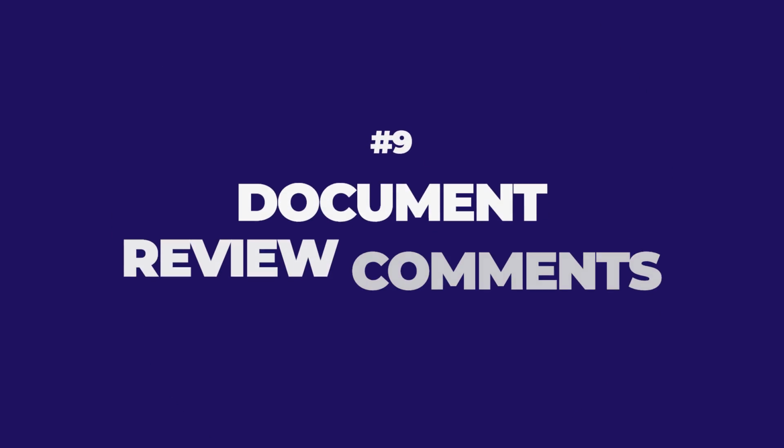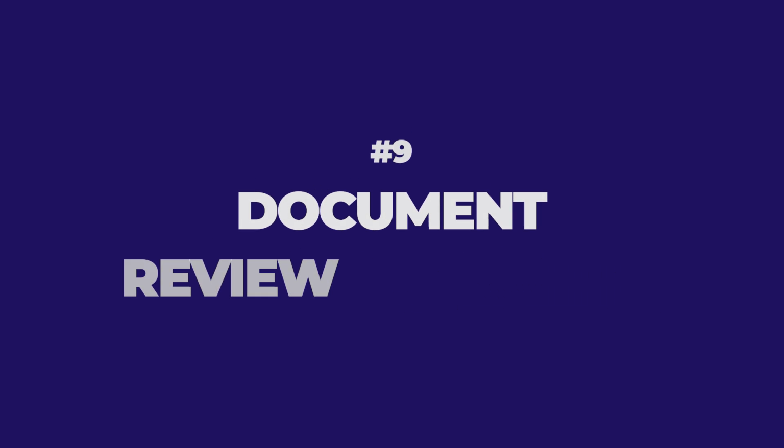Number 9, document review comments. Clearly provide review comments and feedback. And if you can, deal with that issue right then and there instead of not approving it and hitting it back into their court. If you can fix something and make that submittal whole right then and there, especially if it's critical, do it right then and there. But either way, make sure you properly document any comments and provide any actionable feedback.